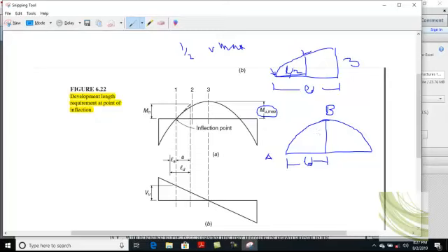if I draw a tangent with this line, okay, so for example, as we know that the bar which is right here has moment capacity equal to 0 because there is no development length. Once the bar covers the development length, it gives you a strength at point B. Clear? So if I draw a line like this, this region which you will see here needs some attention. Clear? Because you can see this line comes out like this.